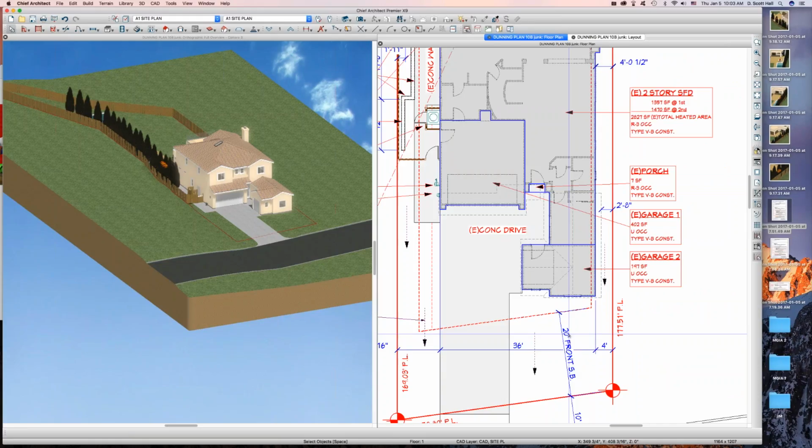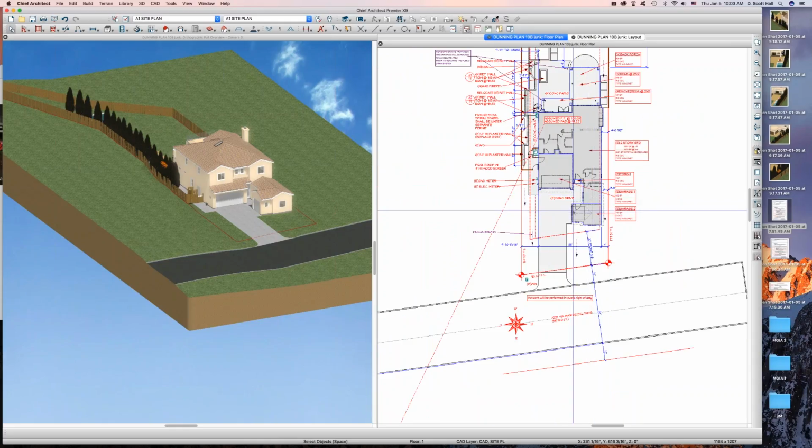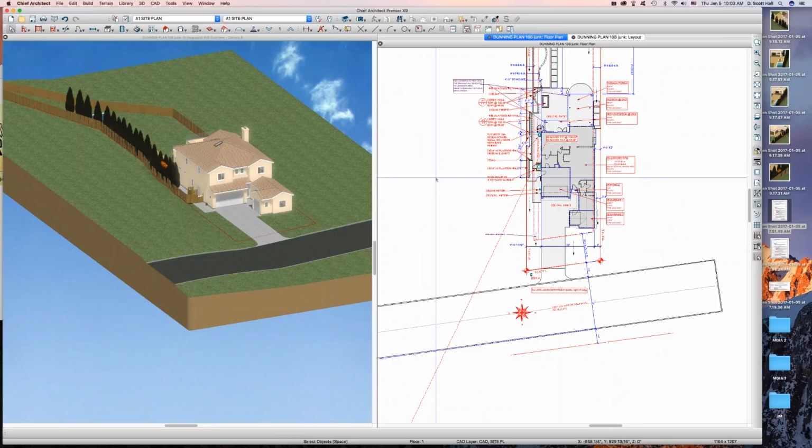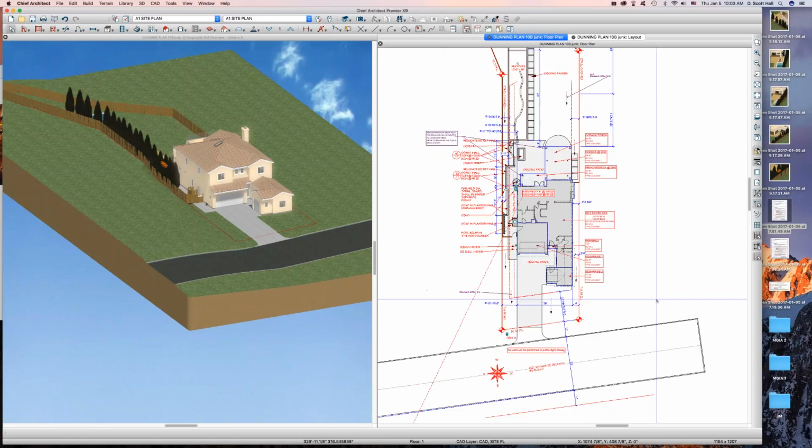So the point here is my buddy, I don't know what the heck he was doing. He was putting a view on top of a view in layout. Just nutty. And then there's the CAD detail footprint method, which I learned there's a reason why it was not a good way of doing it. So my question would be, why wouldn't you do it the way I do it right here? You turn on the right layers, line styles, and use the right ref set. Why wouldn't I use this?